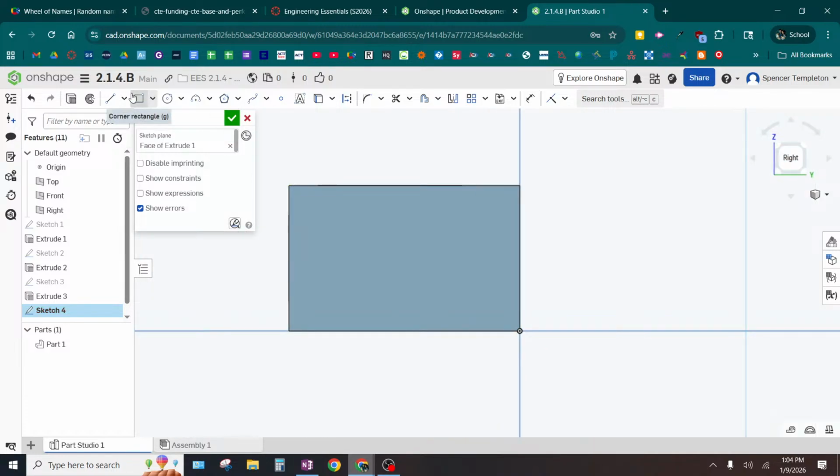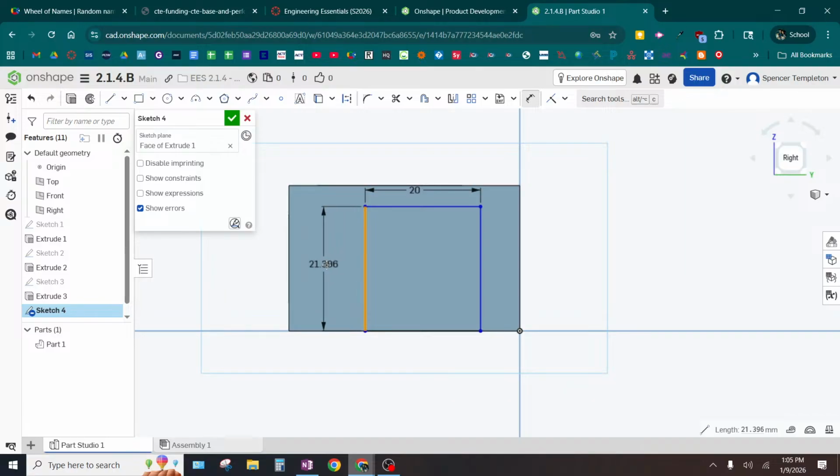I'm going to draw a rectangle. If I start with the rectangle being drawn on this bottom edge, and then I'll lock that in place, then I only need 3 dimensions: a width, and a height, and how far it is from this thing here.